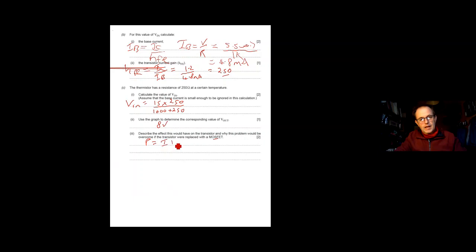If you're in that linear region, you have a collector current and you have an output voltage across that transistor, which means you are going to dissipate energy. You are going to have a power value on that transistor itself, which is going to make it hot. Okay, so heat will come off from that transistor.